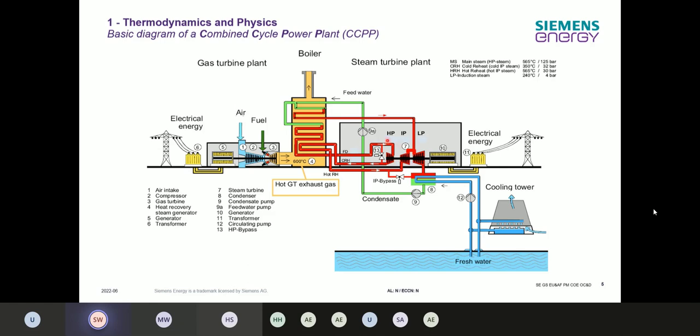Yeah, so we have here the HP high pressure part, the intermediate pressure part, and a low pressure part. That's depending on the turbine configuration. It can also be HP and LP only, where you don't have an intermediate pressure part, like you have it in Shatt Al Basra. So for the water steam circle, we normally always start at the outlet of the condenser.